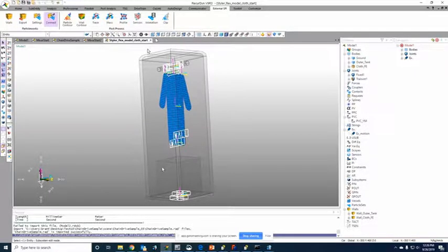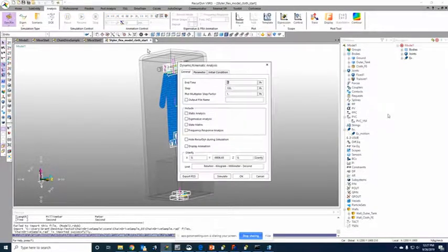And if you have the connect highlighted, then it's going to try to search for a Particleworks file to co-simulate with. So make sure that the connect is highlighted there, and then from there, all you do is you set your parameters for the simulation, whatever you want your end time and step to be, and then you'd go ahead and click simulate. So I'm not going to actually go through and wait for this to complete.